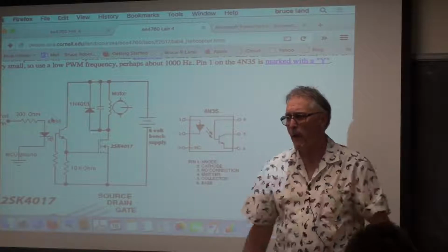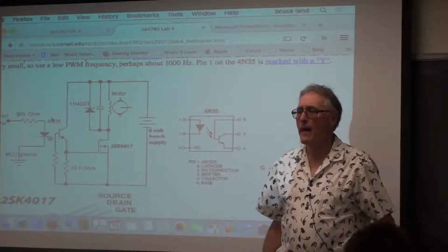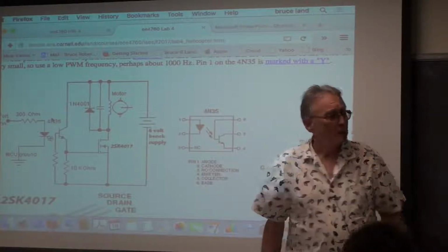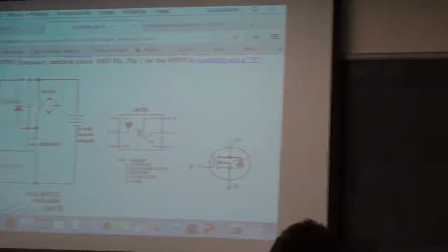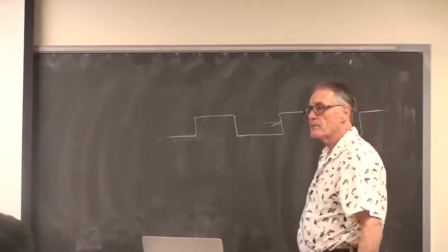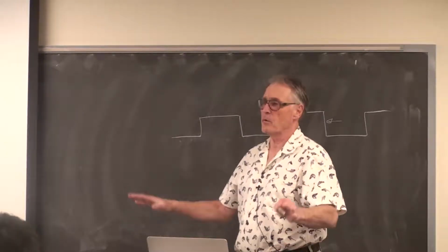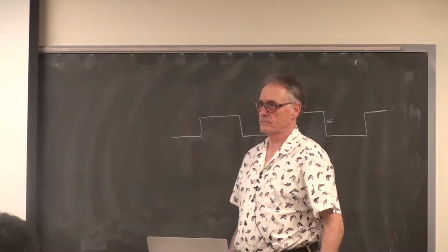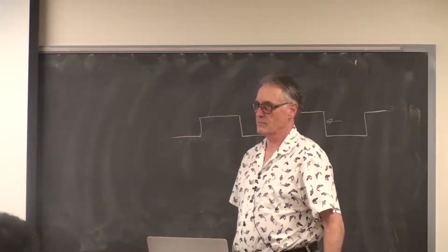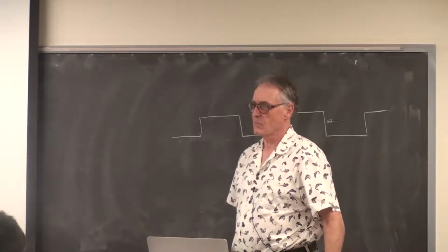Okay, so when you open up the output compare, you pass the PWM on time twice. What does each of those do? Technically, one is this edge, the other is this edge. You don't care about that. You just set the PWM on time. Wouldn't you want one to be the PWM on time and one to be the total length of the cycle minus the PWM on time?